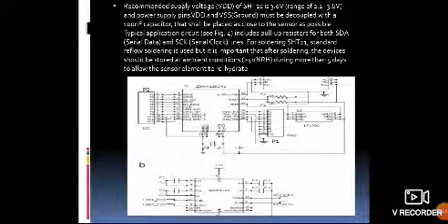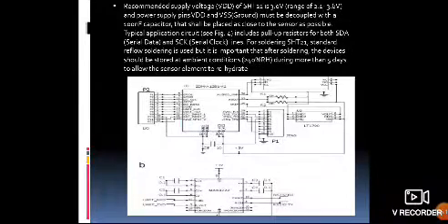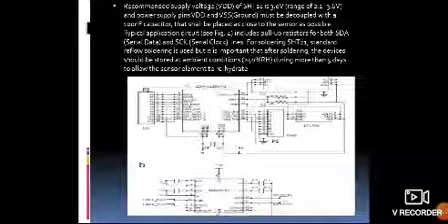The recommended supply voltage VDD of the SHT21 is 3 volts, and the power supply pins VDD and VSS must be decoupled with a 100 nanofarad capacitor that shall be placed as close to the sensor as possible. Here is the circuit diagram for the PIC circuit, and it includes the SHT21, voltage, ground, clock, etc.